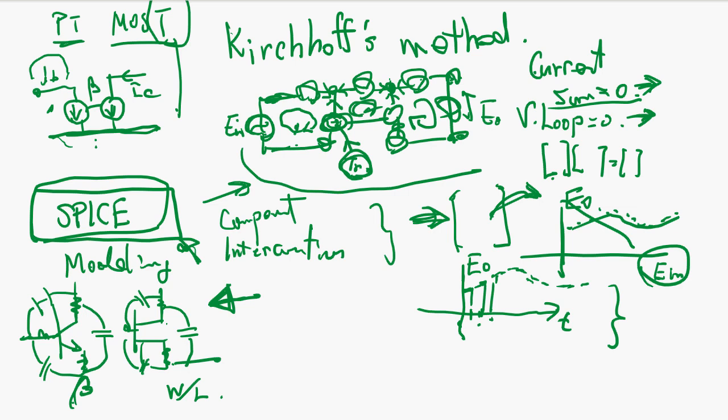So SPICE is going to handle this, and that's why, even with 10 circuit elements, inside the transistor model there will be another 10 components. So it's going to expand really big. But a computer is good at solving matrix linear simultaneous equations. So it just keeps crunching and gets exactly the time domain analysis you want. Input, output analysis, and time domain.